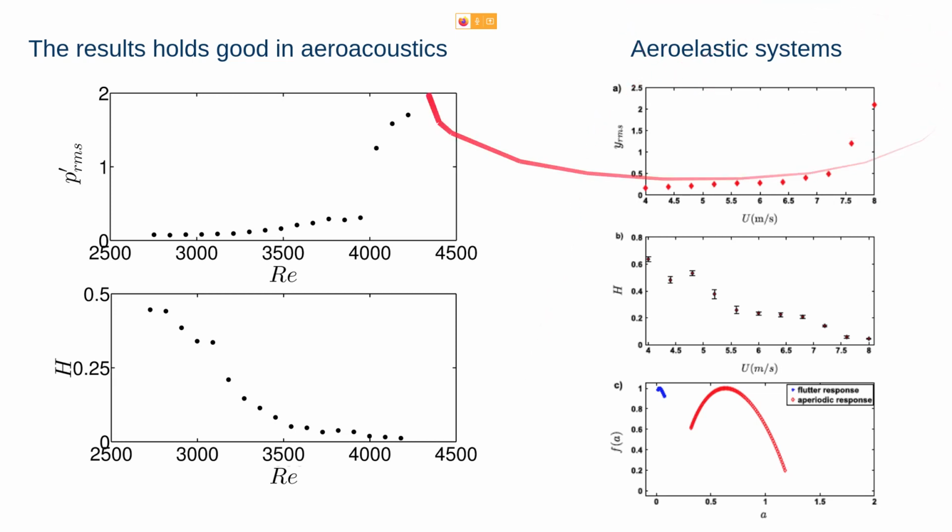Similarly, if you consider the aeroelastic system, the fluttering of wings, or we try to have a fluttering of a small sheet over here, and when you try to measure this, you will see the amplitude on the y-RMS and the velocity being shown over here. Your system initially remains at very low values and it gradually increases to these high amplitude oscillations. Whereas your Hurst exponent values, you can observe that initially it's above 0.5, showing an anti-persistent behavior, and then it slowly comes down, and eventually it decreases before your system actually goes to high amplitude oscillations. It decreases well before the system transits to this.